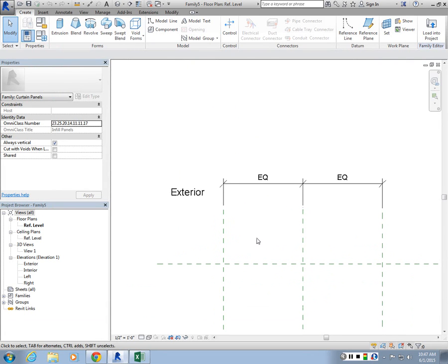Now, if you guys remember when we were doing curtain walls, we were able to define divisions, and turn the division lines into mullions, as well as load curtain wall doors to some of the panels, or make them solid, right? So this is where you can create your own curtain wall panel family, and then apply it to your curtain wall system as well. So you can actually do a lot of stuff with this. You can create it as like a secondary skin, and make it like corrugated panels or some other type of panels. Maybe they're extruded as well, so you can replicate its properties here too.